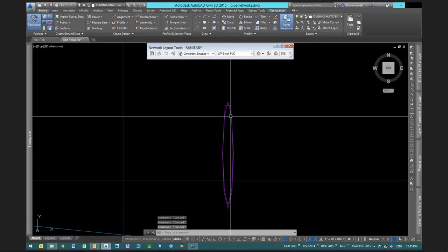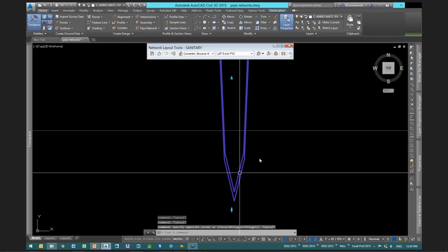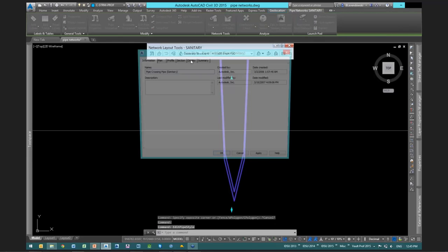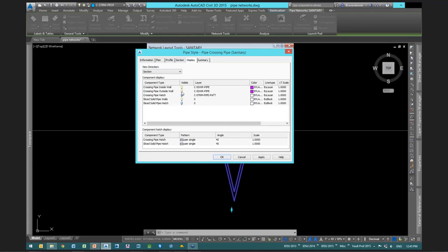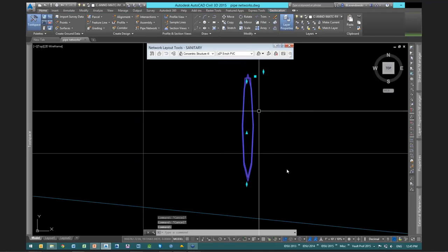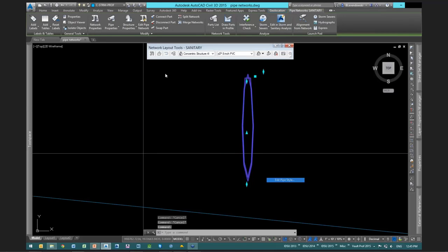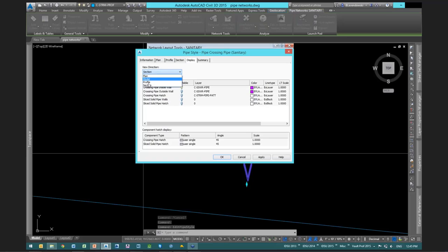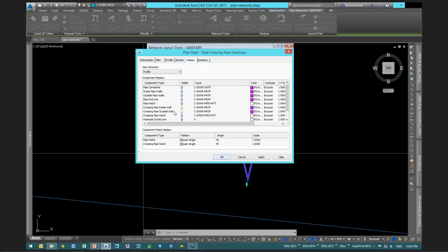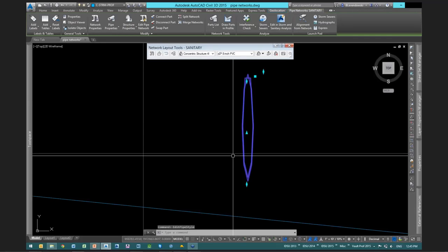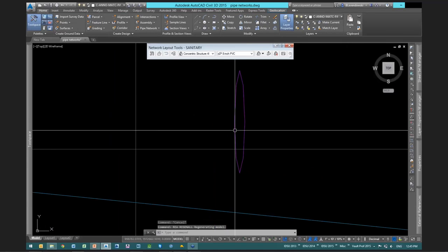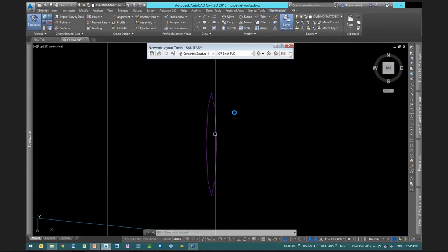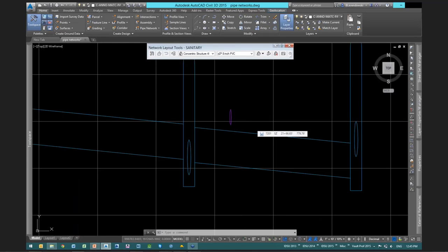And what we're actually seeing here is it's showing both inside and outside wall of pipe. So if I go in here, go to display in the section view, and show perhaps just inside. I'll try that one more time. Edit pipe style, section, sorry, profile view, crossing, outside wall. There it is, a regen. Okay. So when you want more detail than that, it's this system variable, and I should have written it down. It's there. I promise it's there.